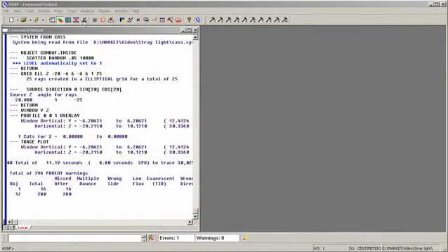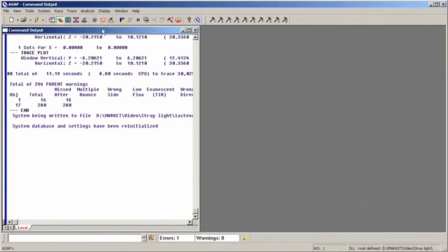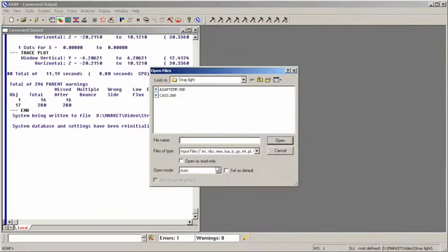Let's take our measured data and fit it to find the coefficients. Let's do this by opening up a file within ASAP. We go over here to our ASAP file. The BSDF fit utility is the application that we're going to use, and we're looking for text files. I have here some text files which represent the measured data for the black surfaces that we saw before.